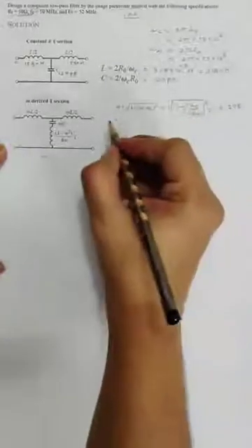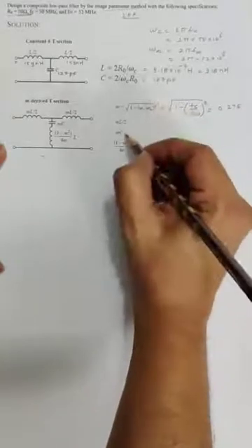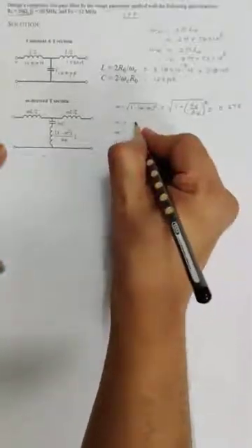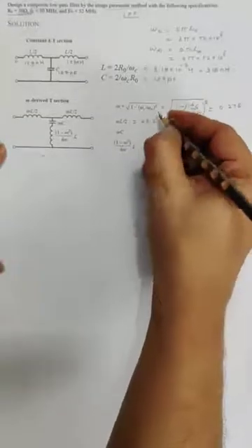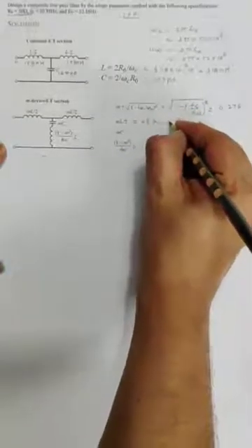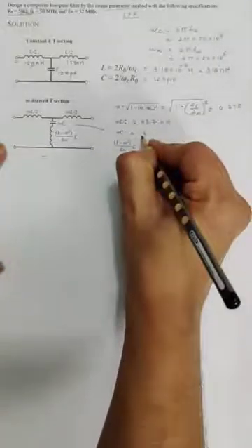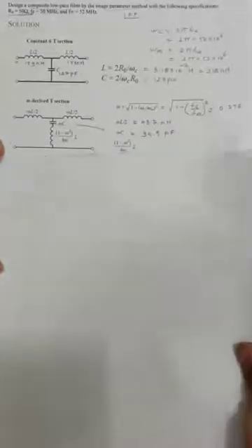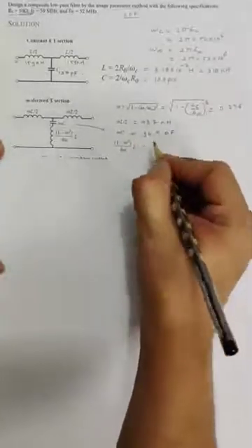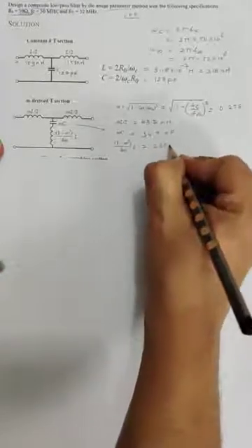So we will substitute these values, L and C from this one, and we can calculate these values. So this turns out to be 43.7 nanohenry. This mC turns out to be 34.9 picofarad. You can check the calculation, and this turns out to be 267 nanohenry.